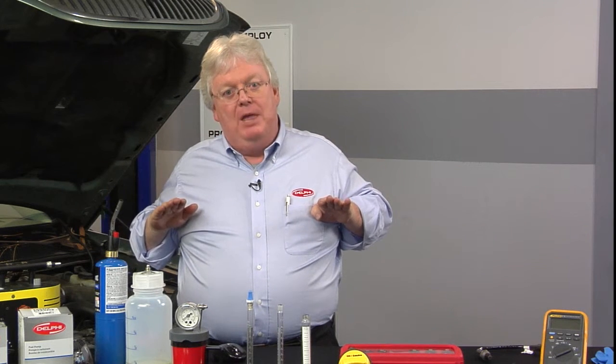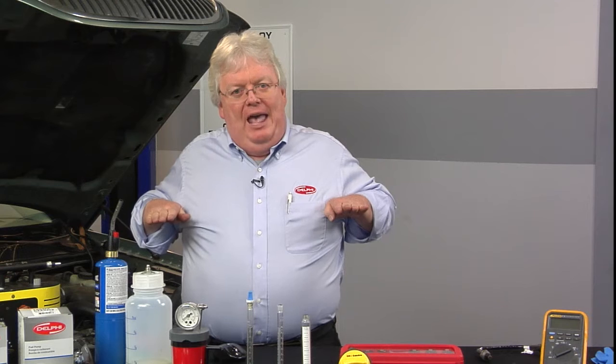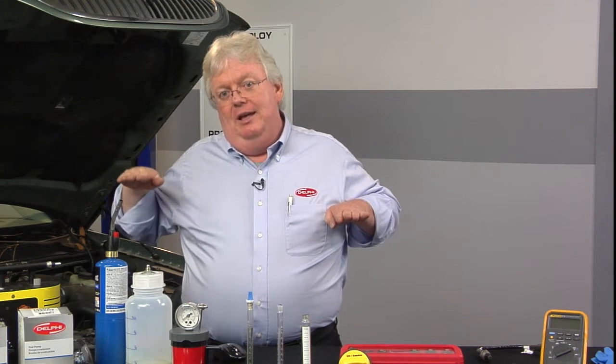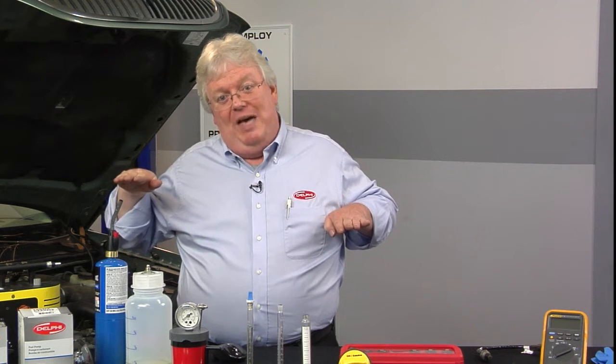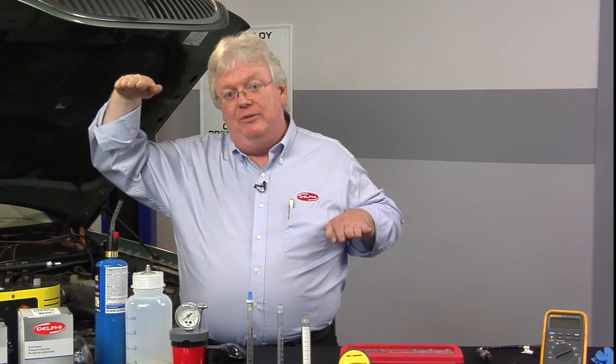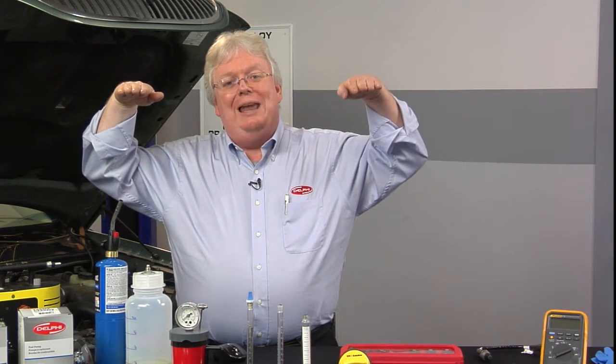14.7, 1 lambda. Below 14.7, richer, below 1 lambda, let's say 0.9. You saw the Explorer, when I put the propane in, it went down a few times to 0.9 as that fuel trim made adjustments before it actually had a chance to make adjustments. And when we started going lean, we went stoich, and the current in the case of the Explorer didn't change much, but out in the real world, in the road tests, without the delays, we would see the current go positive and a higher number of milliamps when the ratio went higher, leaner.